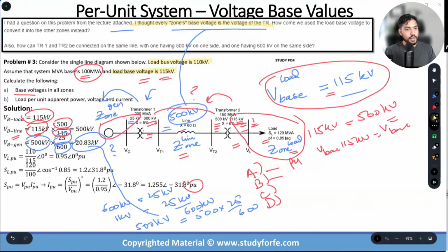And these are the fixed voltages for each one of these zones. And then obviously in the problem statement, I go ahead and explain you a lot of other things. But this is a very important question to understand. And I think in one of the homework assignments, I start out with the fixed voltage in the center of the network, and we go left and right from there, right? Similarly, you can start out with a fixed voltage at the far end on the source side, and then you just keep on going to the right. Does it make sense, guys?